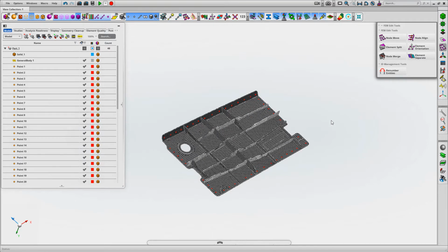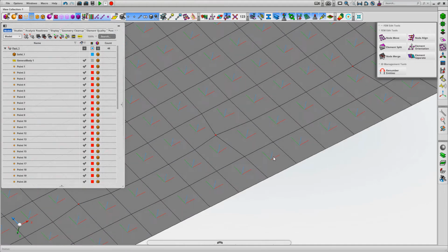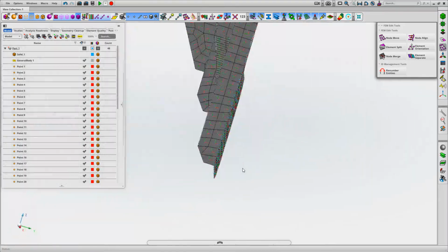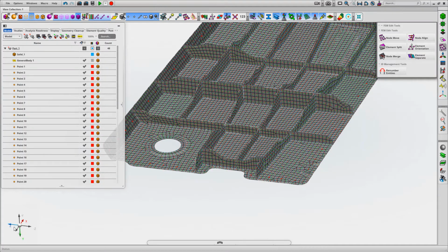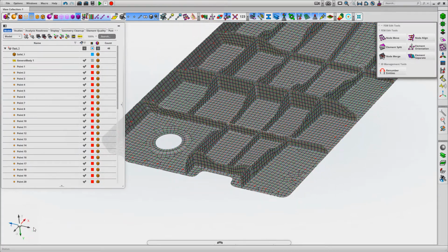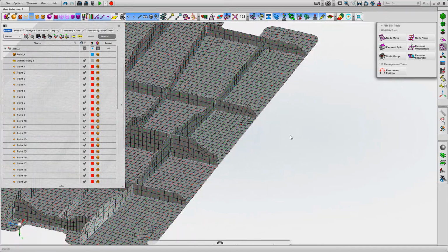We might want to look at the element orientation, so sort of separate from the shell normal orientation. The element orientation is the local element coordinate system, again using red, green and blue. And if you're ever unsure what red, green and blue mean, you can pick them up from the global frame, or coordinate frame defined here. So red is always X, green is always Y, and Z is always blue. Okay, so a couple of things we can do here.